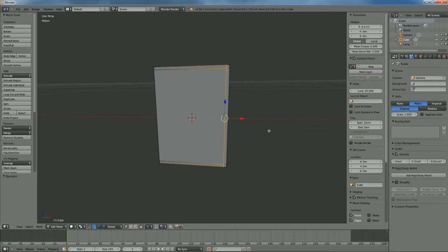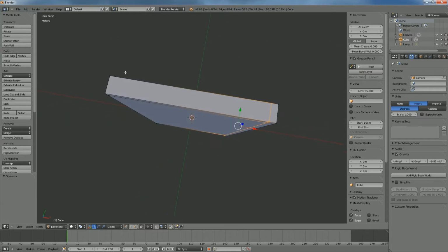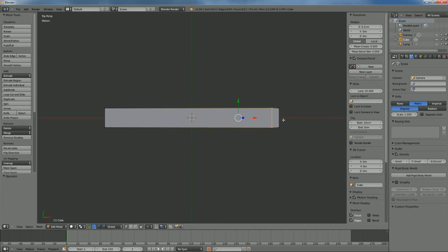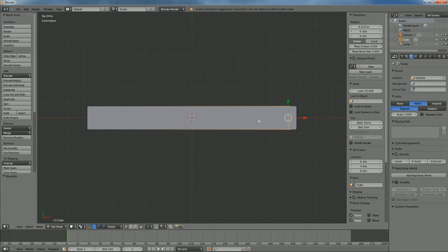After that, we're going to start modeling the lines that you see around the case where the opening is. So we're going to press 7, 5 to go in orthographic, and we'll Control R, right click here, and move this along the y-axis to 0.50767 millimeters.